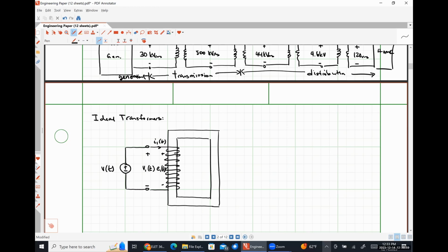but we know that it's happening. In the case of an ideal transformer, and I'll write this part down in a moment, we are making an assumption that our winding or our coil has no inherent resistance of its own. And so that's going to make our terminal voltage and our induced voltage the exact same thing. Here in about half an hour, when we start looking at practical models for transformers, those two quantities are no longer going to be the same thing. So I'm just trying to help you sort out the nomenclature here.